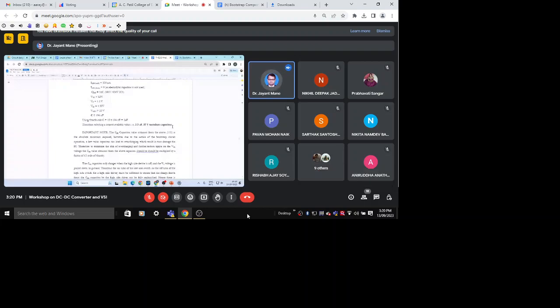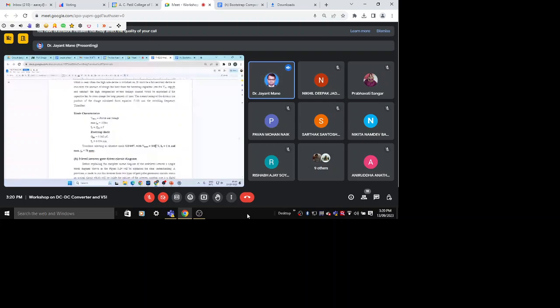And see how this can block up to 1000 volts. Very small diode, but it can withstand 1000 volts. It can carry 1 ampere in forward bias. And TRR, reverse recovery time, is 75 nanoseconds. Therefore, it is ultra fast, very fast. Okay, so the bootstrap diode is UF4007. So in that way, you can.